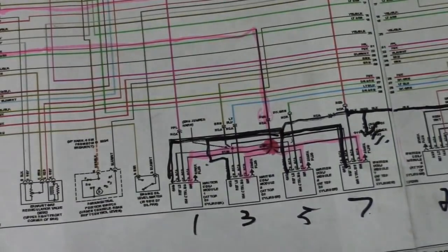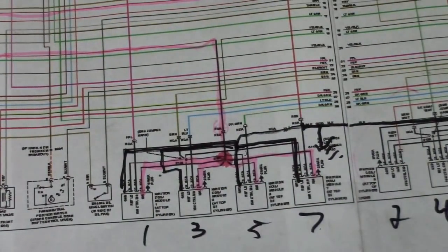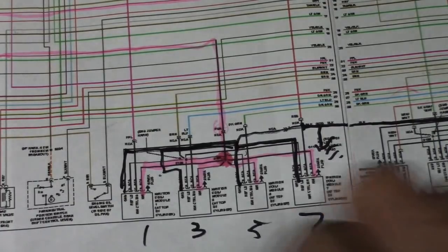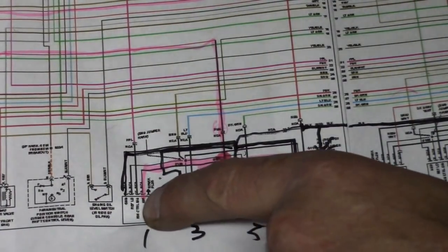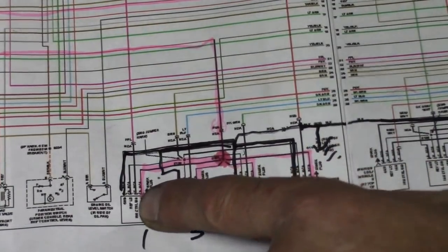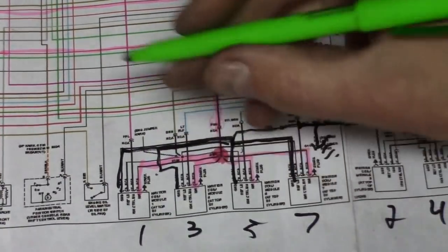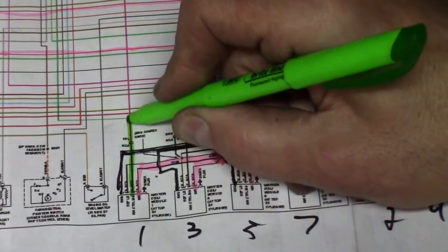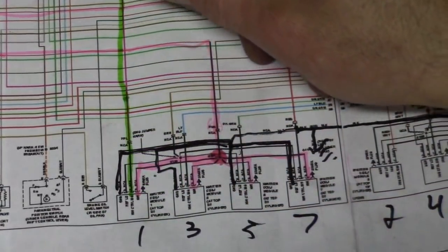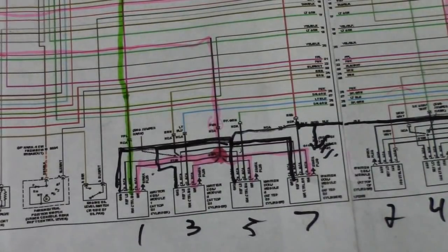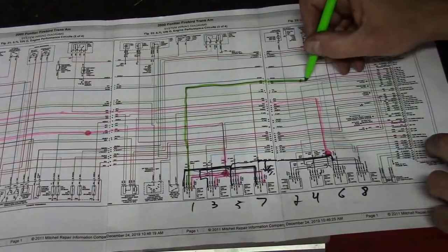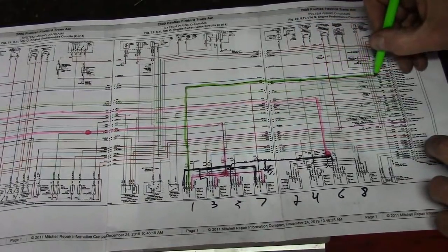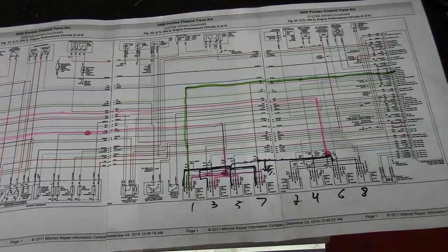What I'm going to look for now is the individual ignition controls. We're just going to look at one of them now. So I'm going to do this in green. And this here says ignition control signal, IGN CTR SIG. So we're going to follow this up. This is going to be a single wire. This is not going to be shared. Moves up the page here. Let's back out. Comes across here. It is a single wire into the PCM. It says ignition control number 1 right here.